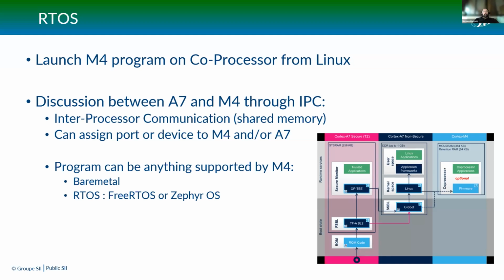And in fact, in the process, we currently build the firmware for the M4, included in the Linux image, and Linux will load the coprocessor. That way, we don't have to also have a specific signature for the M4 firmware to be tested during the root of trust secure boot. So it's directly embedded in the Linux image, which is signed, so no problem about that, and loaded by Linux at runtime, like another process, in fact.